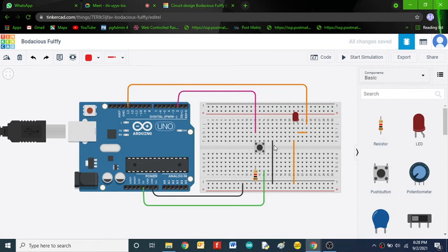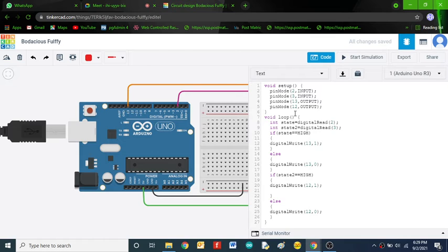Now the point is, you can see the code here. You are reading only 2 values, whether the push button is pressed or not, so you are reading only high or low level logic. Using this high and low level logic, we can build a counter. We have to build a counter variable here, and with the help of the counter variable we can achieve this kind of requirement.